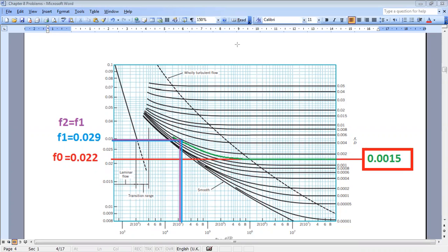But as you can see, you have a major part of this curve that is flat. So a good assumption to start with, because you have a nearly flat curve, means that in this region the Reynolds number is not affecting my result a lot. So a good point to start with is to assume the friction factor equal to 0.022.